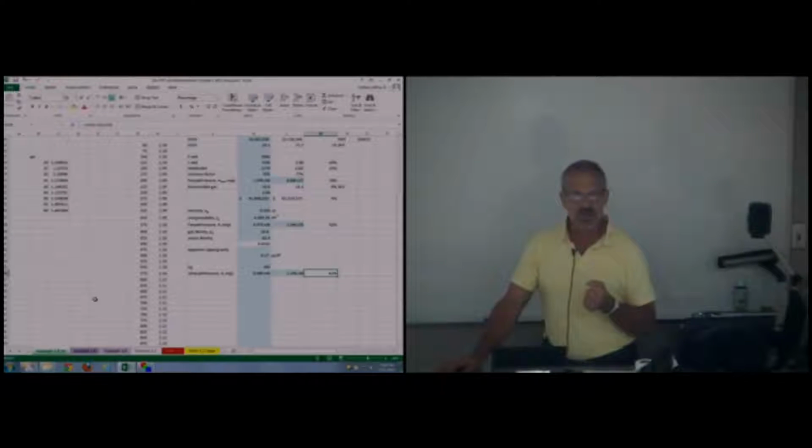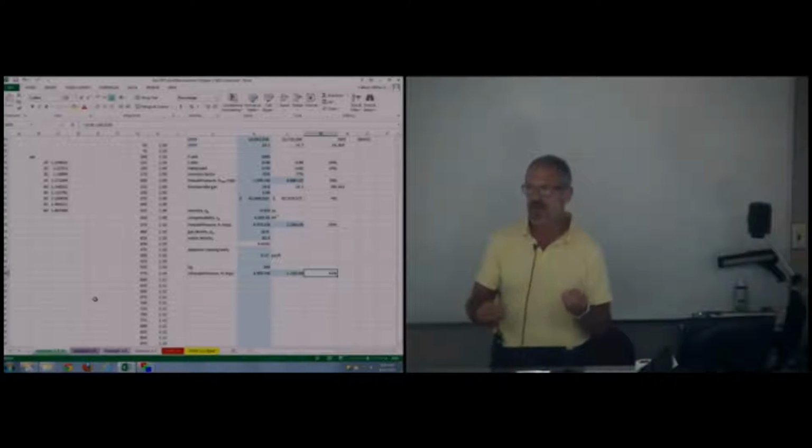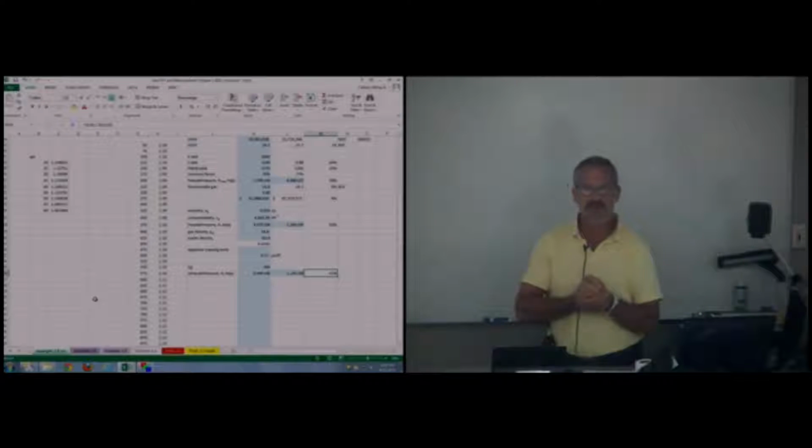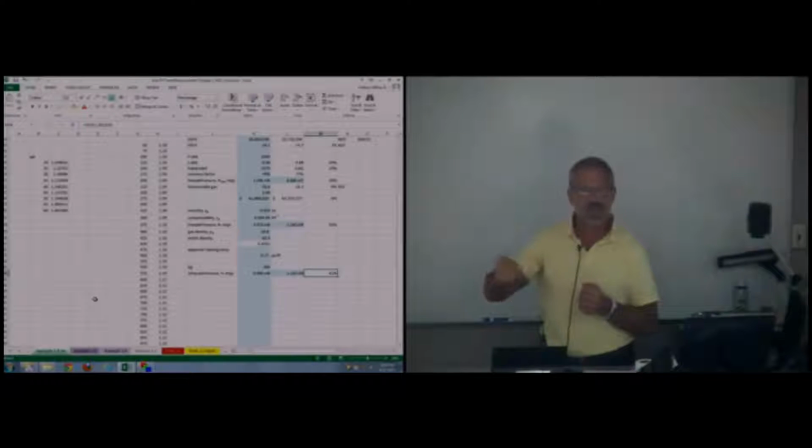if you know its pressure at 2 different points or 2 different depths, and it's linear, then you have a gradient. You can multiply that gradient times 144 to get its density, and vice versa. If you knew the density, you could divide by 144 and get the gradient. My units here are pounds per cubic feet for density, and PSI, or pounds per square inch, per linear foot. How much the pressure changes each foot we go deeper.